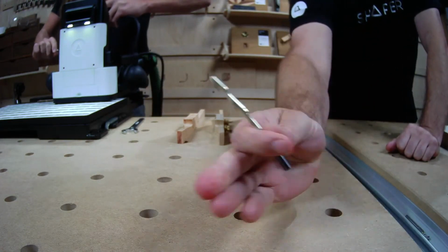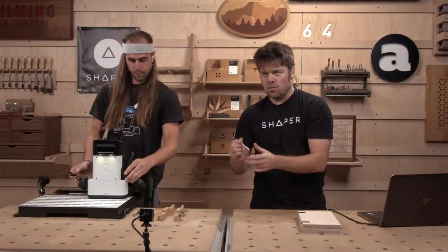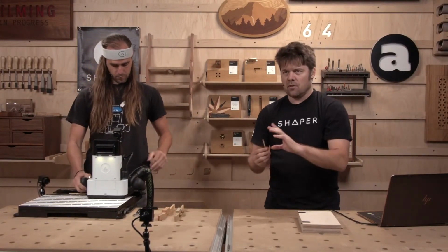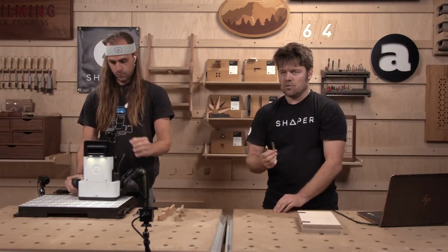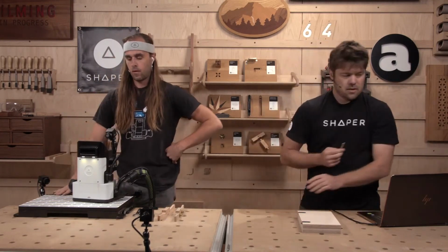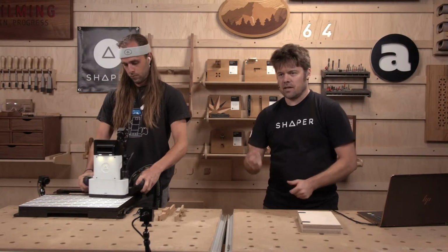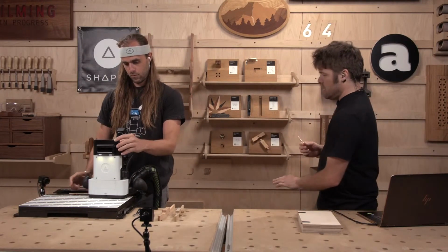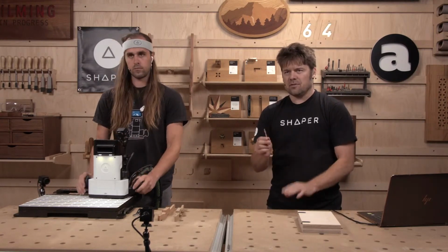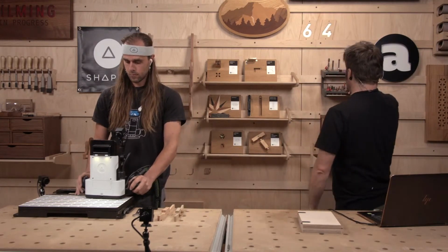So you end up with chatter and reduced cut quality when you cut very deep or load it up in hard material. If you're working with really soft material, long cutting flutes often work fine. People use quite long cutters for foam, and if you're doing any of our Sys1 box installs, a cutter like this would be epic. But once you're into harder woods and things, those long cutting flutes are not as fun to operate, and the cut quality deteriorates as a result.